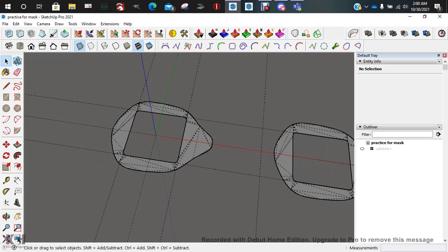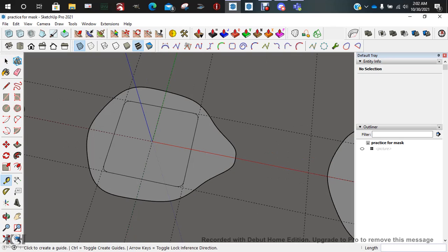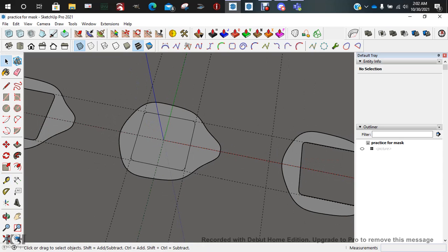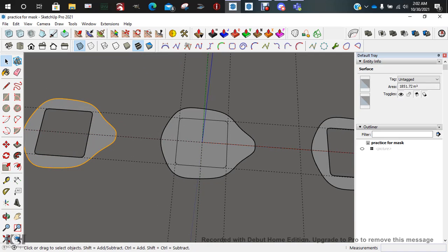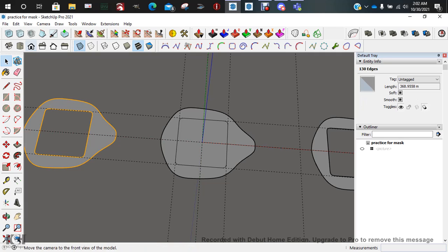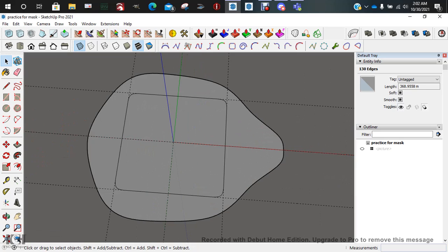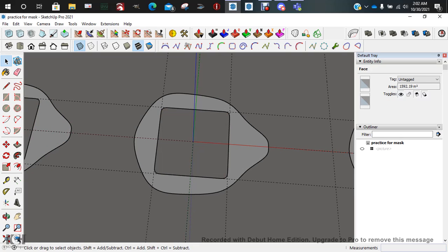Okay, give me just a minute to clean some of this up. Okay, all I had to do was I just copied the lines here after I welded them, Control Copy, moved this out of the way, and then did Edit, Paste in Place, which brought it here. And then I just drew a line across, which completed the surface, and then I deleted what I didn't need. And now I just need to get rid of that face. So now I can push pull.